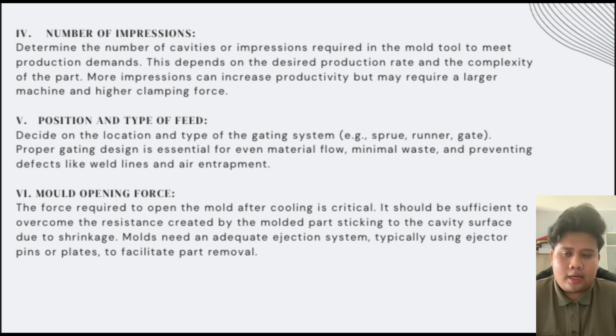Number 6, mold opening force. The force required to open the mold after cooling is critical. It should be sufficient to overcome the resistance created by the molded part sticking to the cavity surface due to shrinkage. Molds need an adequate ejection system, typically using ejector pins or plates, to facilitate part removal.